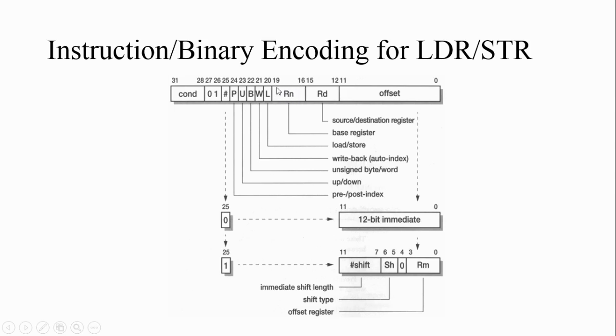That means if you write 0001 here, you can identify that you are going to store the base address in a base register known as R1. Similarly, the 12-bit offset will be given directly here. Whatever 12-bit immediate value you want to give, you give it here, right? By adding the base address and the offset, you get the resultant address, which is the address of the memory. From that memory, you read the data, and that data should be loaded into a destination register.